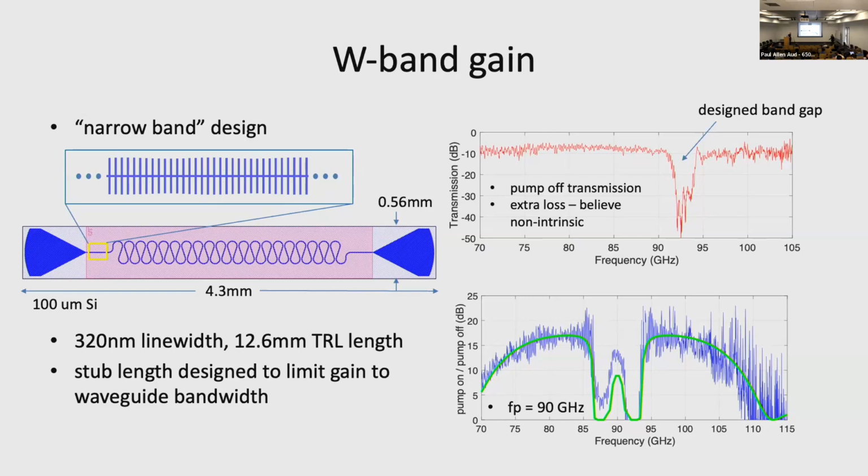Yes, there are a number of ways you could compare them. Certainly, the kinetic inductance nonlinearity is not as large as you can get with the Josephson junctions, but I think in practical cases the loss in our paramps is less than in a Josephson TWP because of the more complex fabrication.